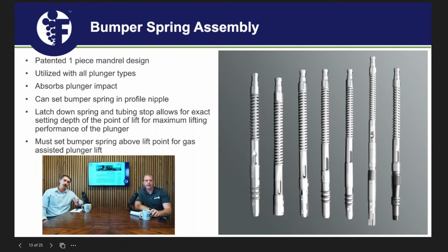We have the tubing stop pictured right here, and we have pictured here the tubing stop on the spring. My experience is that's not a great idea. That tubing stop just has slips, and the way you set it is you hammer down on it, and the more you hammer it, the more those slips get pushed in, cutting into the wall of the tubing. When you do it with a spring, that spring tends to absorb a lot of that hammering and jarring you're putting on it.